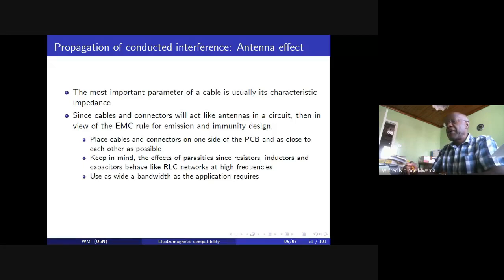And therefore we make our amplifier to amplify very nicely from 10 hertz to 20 kilohertz. But most of the information is usually in the lower ranges, and in the higher ranges there is not so much, because those are what the ear just uses to put in the detail. So instead of making it that large, we are going to make sure that we just use as high a bandwidth as the application will require.